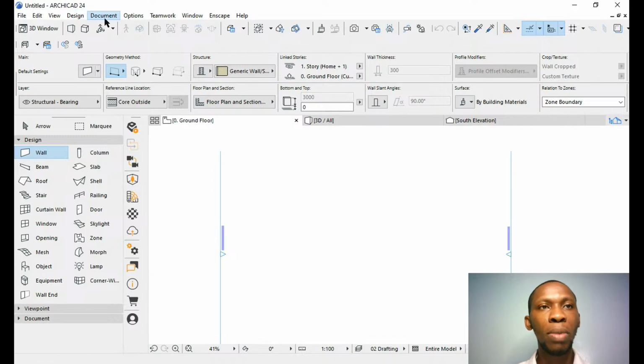So we have documents. Next menu we have document. Under document we have documenting tools. Right, so now you can see, just like we checked this menu here for the navigator, we saw elevations, sections and all that. So here you can select or start working on the elevation of a particular project, or section, or interior elevation. For interior designers, right?